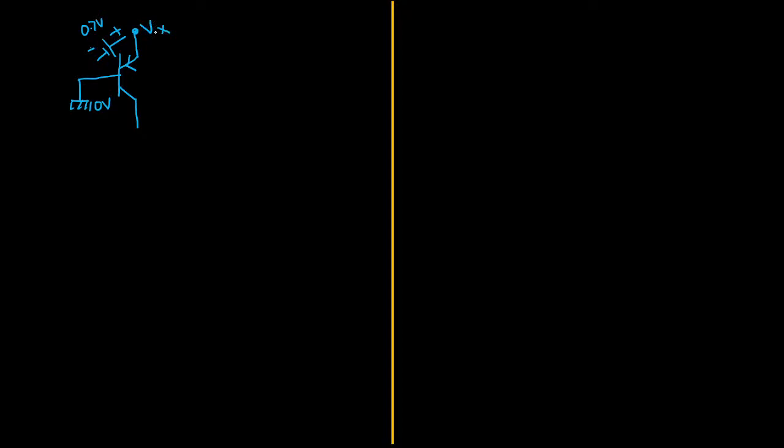Here I just wanted to know the value of Vx. How will you do that? Vx means that is plus Vx only. I'm just assuming that is plus Vx. How will you do that? So if I redraw this circuit like this, can I draw? See, I'm starting from ground. First, the base terminal is connected to the ground. Then I am crossing the diode. The diode will be written like this. Then I am reaching one more voltage that is called Vx.